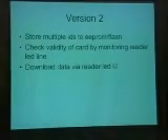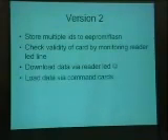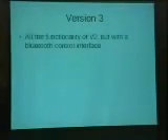They check the validity of the card by monitoring the reader LED, so there's a slightly better one here, which has another connector on the top which intercepts this LED line. That's my fave. It is serial port, line 5, clock the data out, and it will load the data via the command cards. Version 3, I'm using a Bluetooth interface.